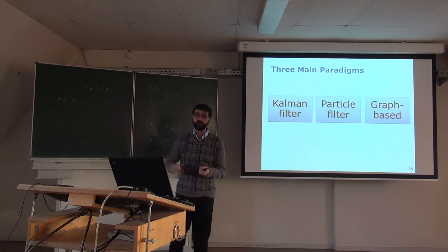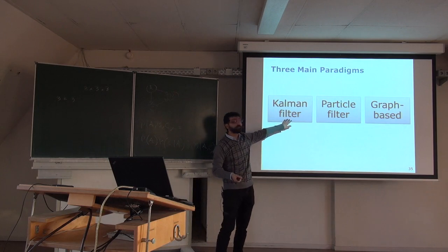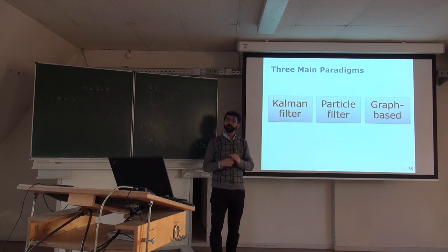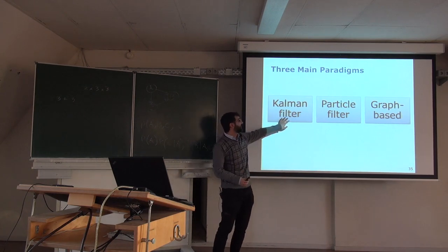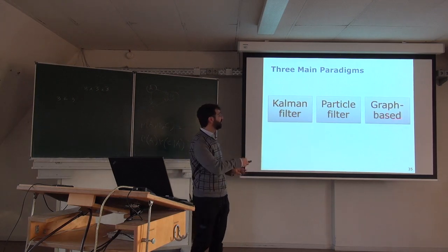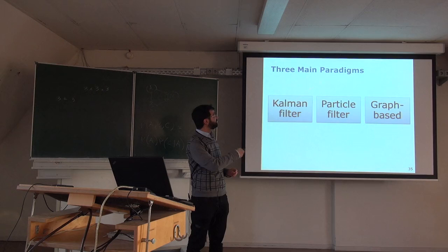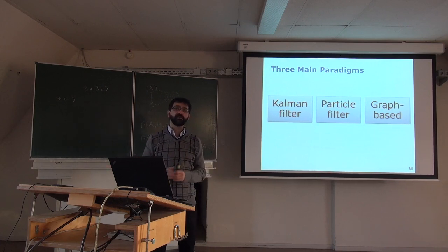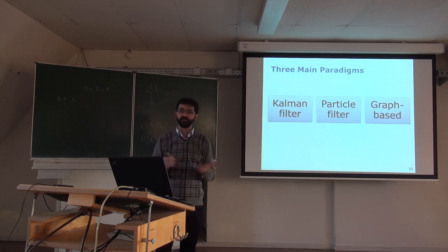Okay? This is something that also happens in the Kalman filter through the correlation that I've shown you before, because everything is correlated. But if we have a nonlinear system as we have, the things are not exactly the same. So you can find, under certain assumptions, that the full batch optimization and the incremental optimization are giving you the same result. But unfortunately, these assumptions do not hold for a real world with a real robot. So you can talk about them theoretically, but in practice, they do not hold.